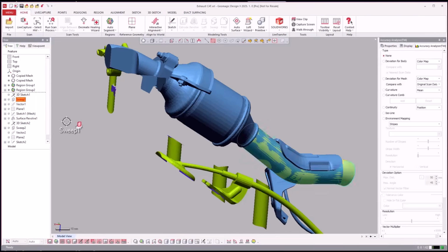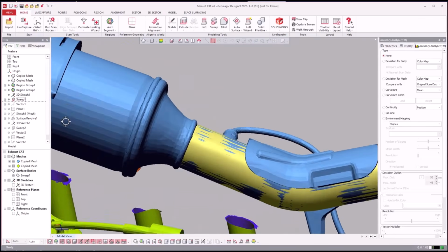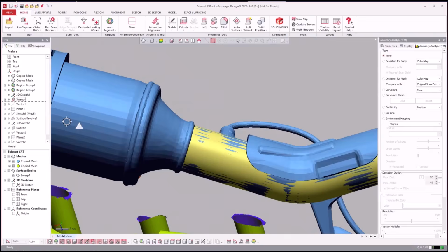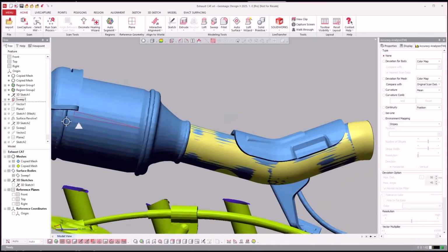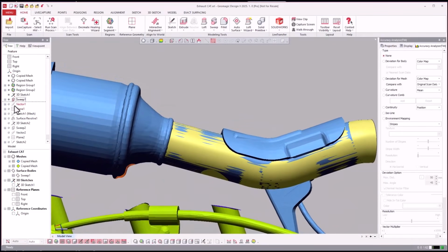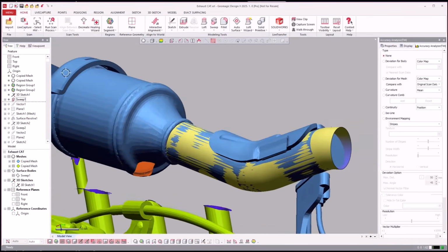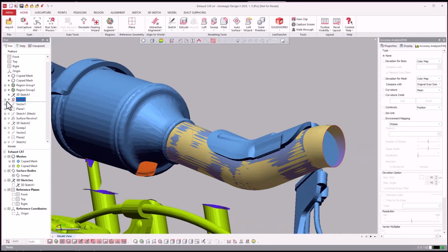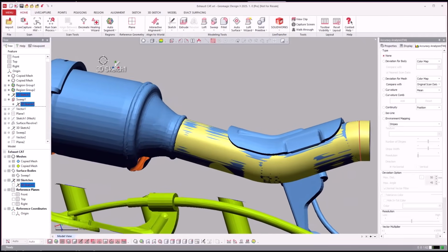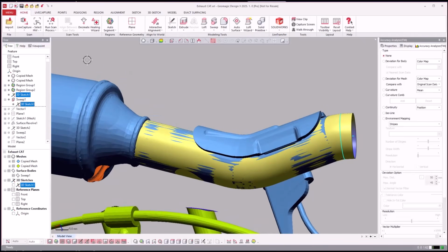So the first thing that they did is they went ahead and did a sweep on this data here. And honestly, most of the time that we do these sweeps so quick where it's a 3D sketch, if you see a 3D sketch and it's all self-contained like that, almost 100% of the time it is us using our sweep wizard or the pipe wizard, which is right in here.